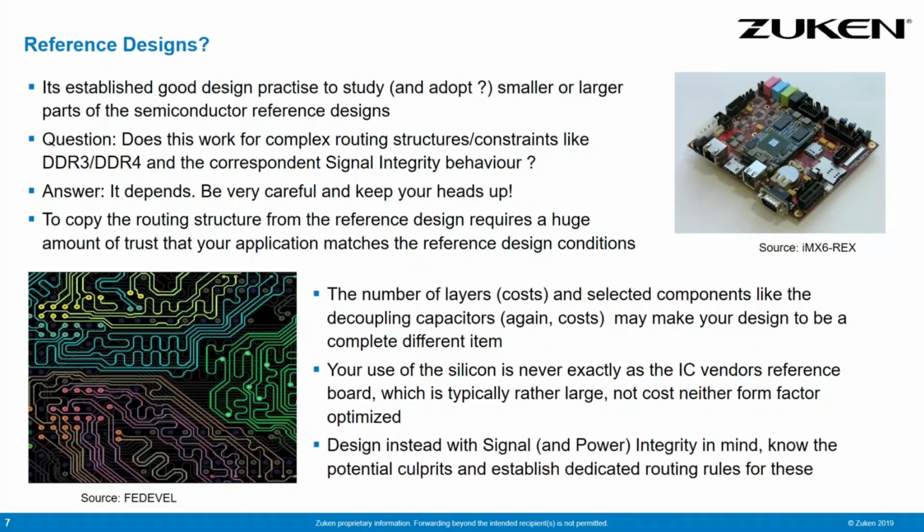The boards are typically rather large. Instead of doing that, I do recommend designing with signal integrity in mind and, of course, with power integrity in mind. Know where problem areas are, establish design rules addressing these problem areas, and avoid traps and pitfalls.